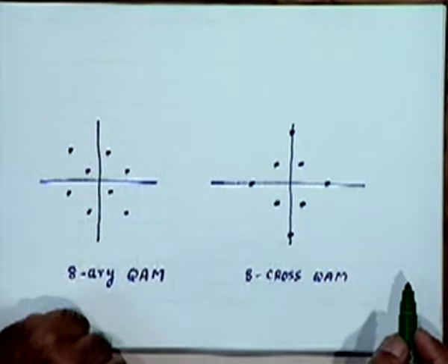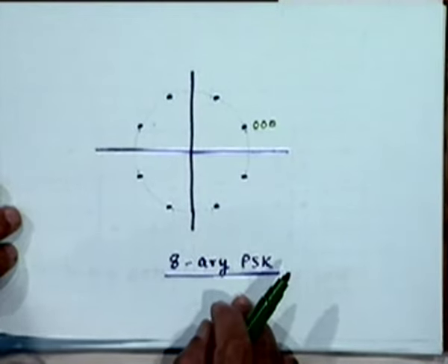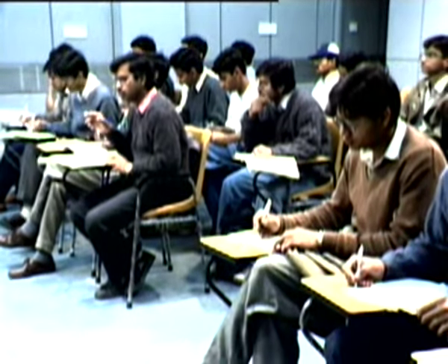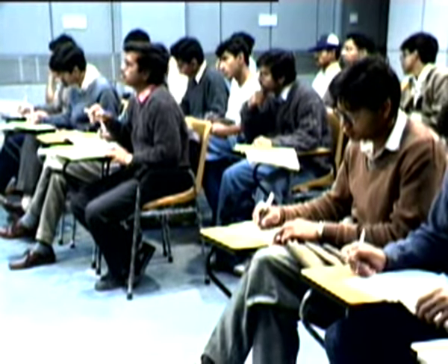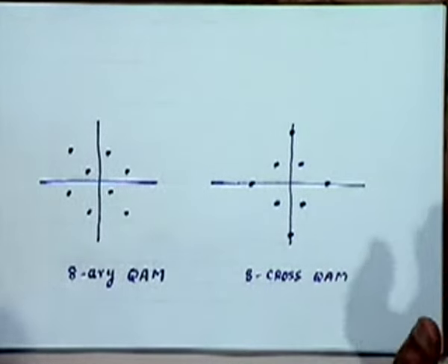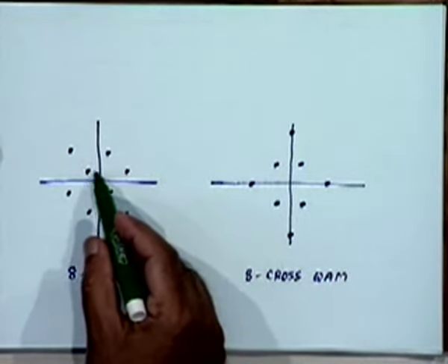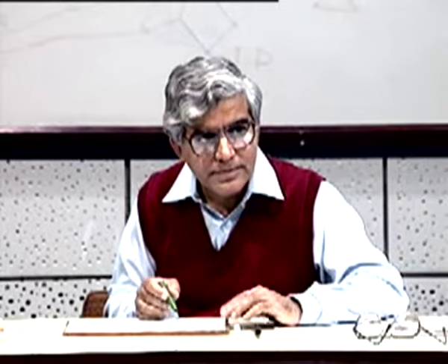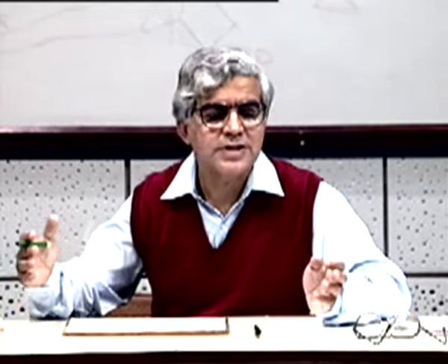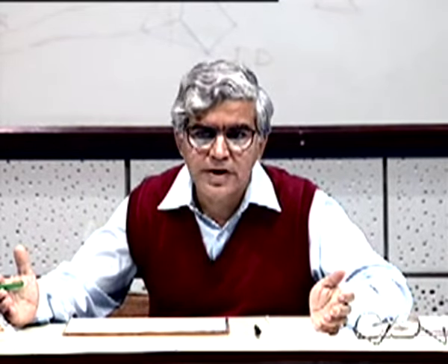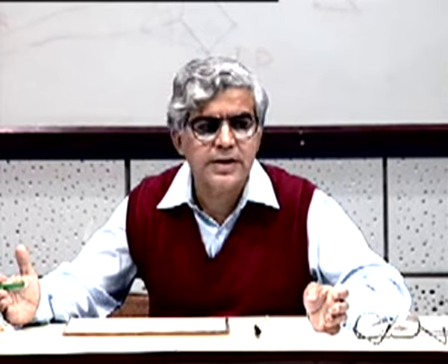If I have the same amplitude for all of them, I get back to PSK. Even if we assume that the phase is not uniformly distributed, it may not be. In this case, it is not uniformly distributed. In general, in any general QAM modulation scheme, the phase will not be uniformly distributed. Even the amplitude may not be uniformly distributed in some cases, for example, as you can see here, right? You have an infinite choice here. It's up to us to choose a constellation to represent the given number of bits that we want to encode or use for modulation at a time.